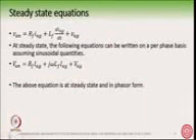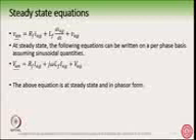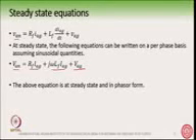Of course, now we are talking about steady state. The equation in differential equation format is like this. VAN is this one, but at steady state we can write this equation on a per phase basis, assuming all quantities are sinusoidal. These are phasors, so we write the phasor equations. L di dt becomes j omega LF IAG at steady state. These are all phasor quantities. So VAN is RF IAG plus j omega LF IAG plus VAG.